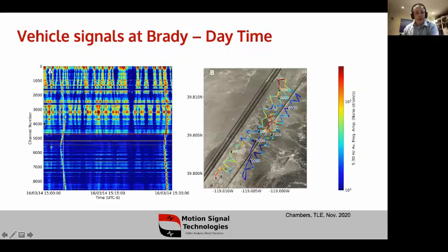We're now seeing much higher amplitudes. The plot is looking a lot more busy on our first 4,000 channels. In fact, we're seeing many cars go backwards and forwards, and the signals are all overlapping each other, creating a really complicated interference pattern. You're even seeing a couple of signals which stretch right across the array, and these are probably cars traveling along the frontage road that runs through the middle of the array. But the majority of the traffic is happening along that highway, unsurprisingly, and it is busier during the daytime.